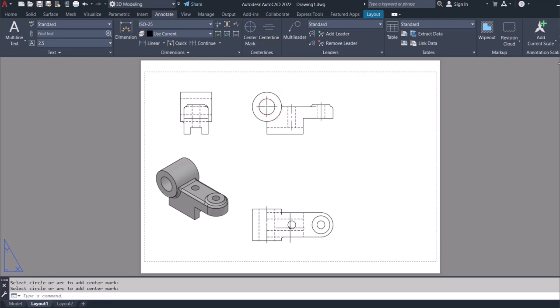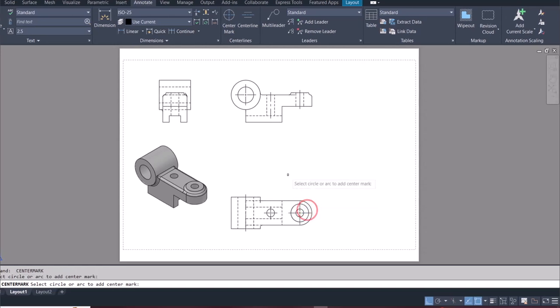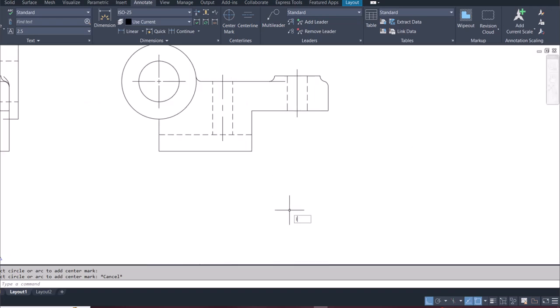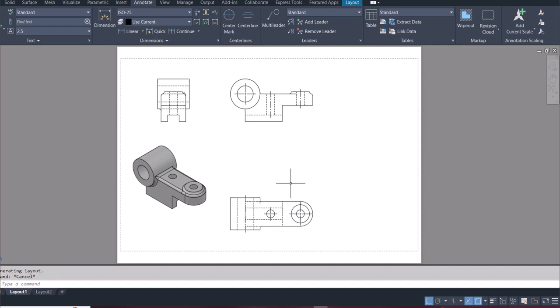Another one, another one there, and then yes, still we can have another center mark here. Okay, all right. So for this, if we did the LTS and then change this to maybe 0.5 now, we can see the center lines well. So Z enter, A enter. Here I haven't put in the center line because there are a lot of hidden details. I don't want to overcomplicate it.